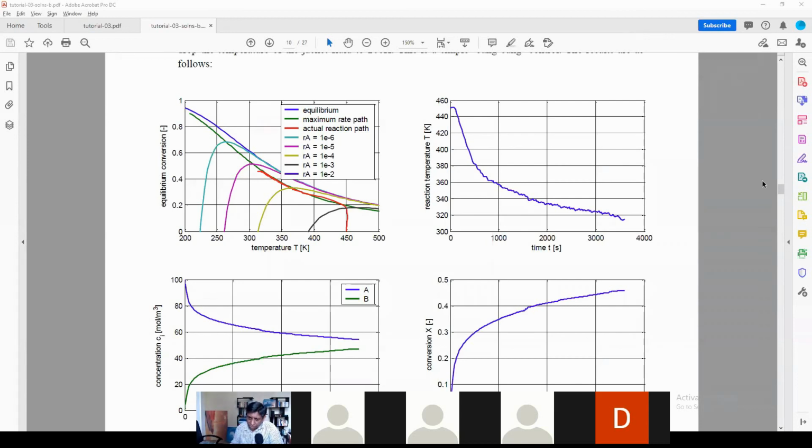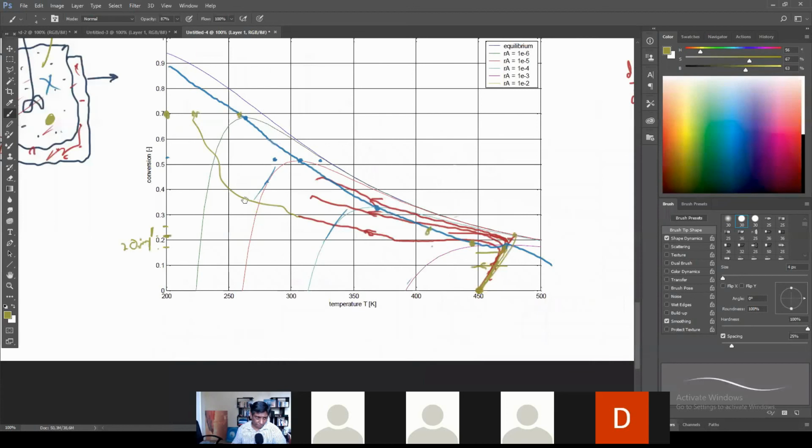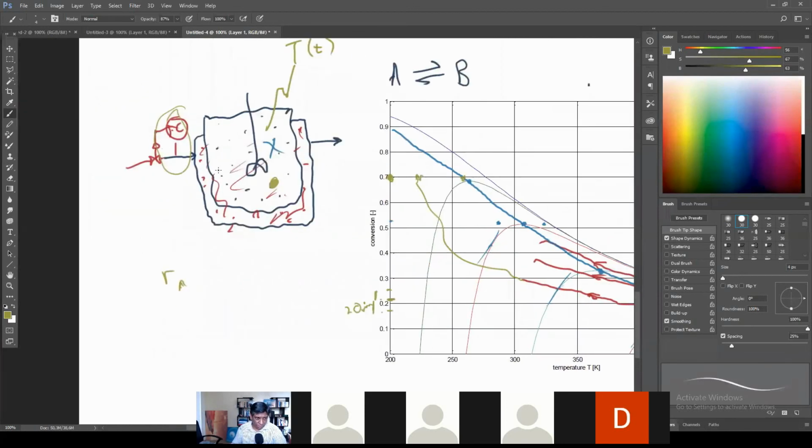Oh, one second. If the flow rate for cooling is too high, then the trajectory takes too long to reach the conversion, so apply initial cooling instead. In terms of this question, number one, yes, it might be the case that the flow rate that you apply is not good enough to change the temperature in the jacket quickly enough.